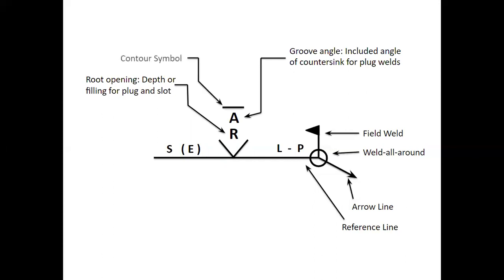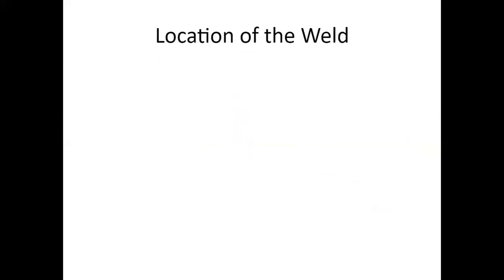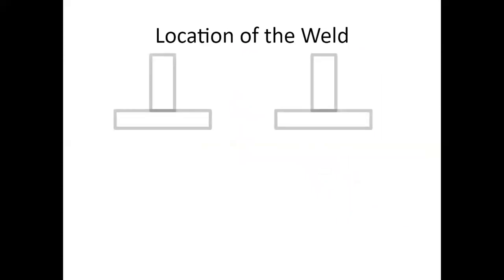It's going to be a finish symbol. It's a flat contour. Oh, finish symbol is the top one. Sorry, the last one's the contour symbol. Finish symbol is going to tell you how we are going to finish out that weld. Sometimes we're asked to do things that seem contradictory, like chipping or peening. That's going to basically beat up the weld, but it has a purpose. It'll probably be stress relief, the big one on there. But I don't beat up welds unless I have to. I try and keep them looking pretty.